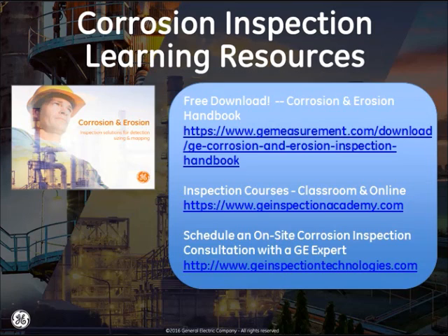Thanks, Dave. And Johnny, is there any application on stainless steel sheet material, 0.2 millimeter thick, for radiography? Yeah, I think when you get into pitting, that's a tougher type of application to quantify and measure. So I think we can definitely discern if there's some wall loss. But if you get into some very fine pitting in that type of material, I think you're much better off going with either RVI internally or UT externally.